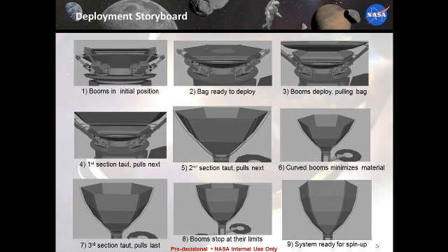We put together an animation. It didn't run so good in the program or in the slide set, so I did some screenshots. There's 6 actuators. They're real type deployable booms, similar to Northrop Grumman stem booms, which work similar to a tape measure. When you pull a tape measure out, it goes from a coil configuration out to a rigid shape because of the cross-section changes as it comes out. So as these extend out, it would pull the bag up and out.